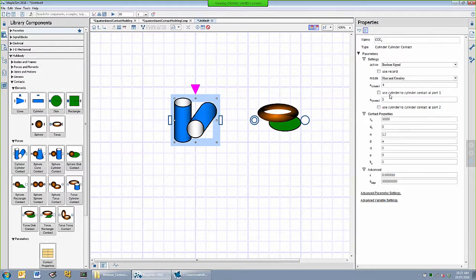The utility of that is, for these 4, you can ask to automatically include contact between them. So you can have 4 contacting 5, all combinations. On top of that, you can have those 4 contacting each other, and the same for the 5. So this way you can organize with one component what contacts what, if they are all cylinders.